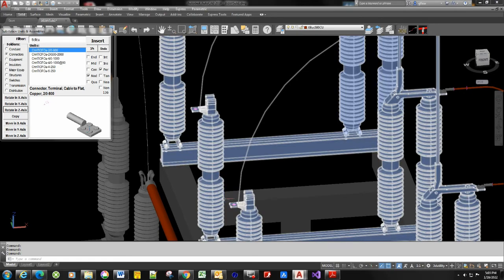A clamp type connector. So let's go back up here to our connectors. It's still going to be a terminal connector because we're terminating that pipe bus, but this is going to be a tube to flat. I'm sorry, it took me a second to even figure out what I was doing. We're coming from a tube bus to a flat pad, and here we're just going to go down here and pick the 4-inch. So we get terminal connector, tube to flat, 4-inch.